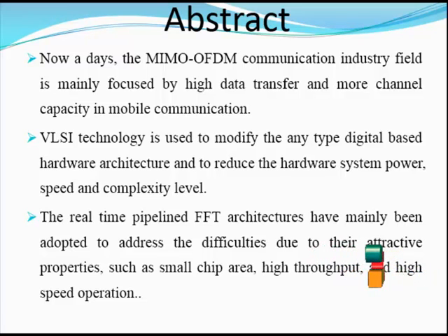Fast Fourier transform has played a significant role in the digital signal processing field, especially in advanced computation systems such as orthogonal frequency division multiplexing and asymmetric digital subscriber line. All these systems require that the FFT computation must be high throughput and low latency. Therefore, designing a high performance FFT circuit is an important solution to the above mentioned problems.